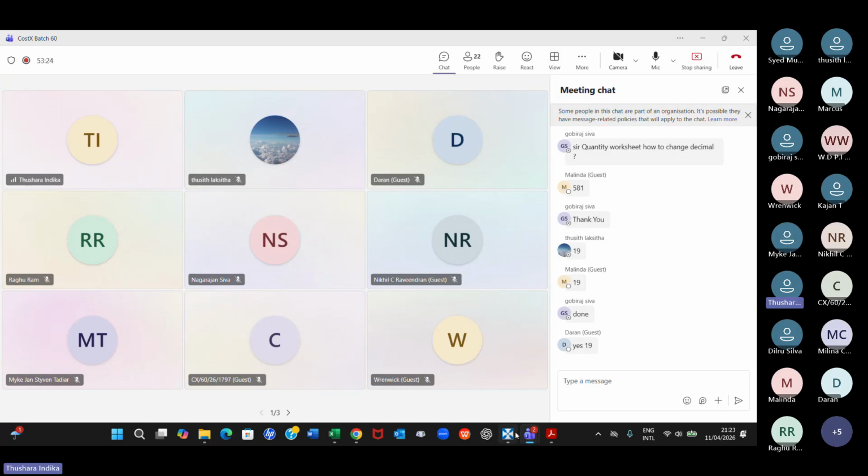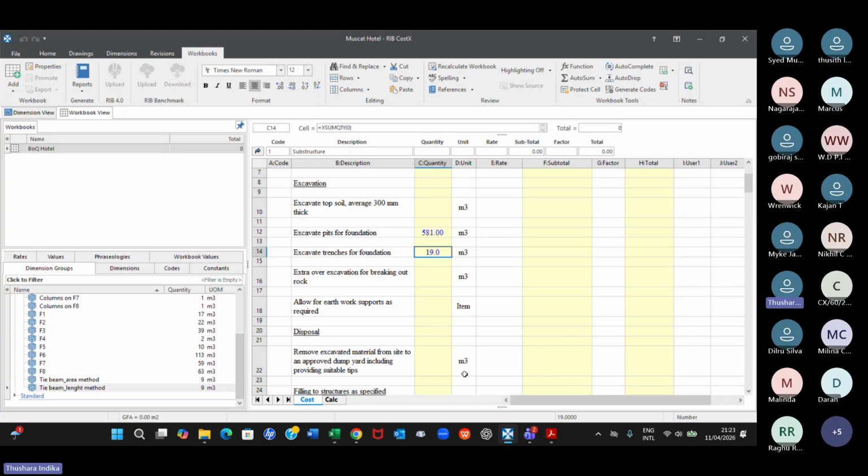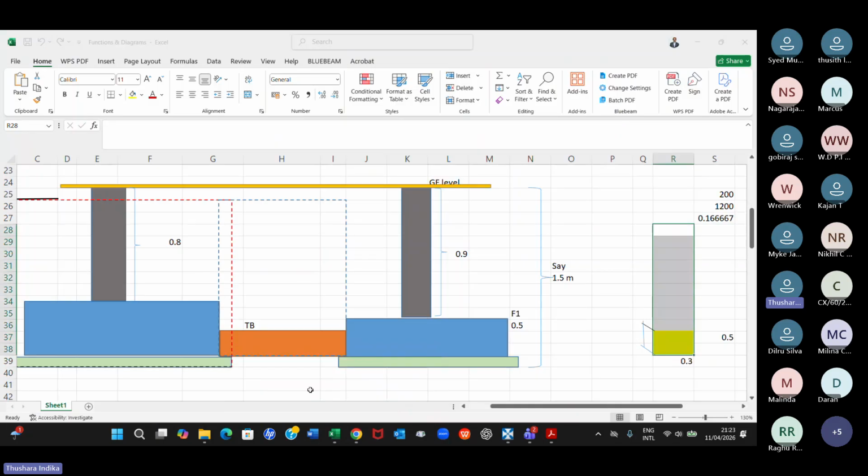Somebody must be arguing if it is a kind of, let's say, measured and pay contract. In most of the cases in Sri Lanka, contract type would be going as the payment mechanism would be going as measure and pay. Right, quantity can be remeasured. Then you don't have to even deduct these overlaps. You don't have to deduct these overlaps because we know the quantities are to be remeasured, and this is not a big amount. So you don't have to deduct in your day-to-day measurement.